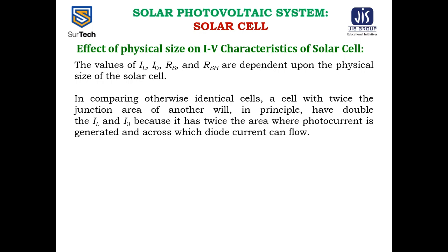Since the changes in the currents are the dominating ones and are balancing each other, the open circuit voltage is practically the same. The VOC starts to depend on the cell size only if the shunt resistance becomes too low.